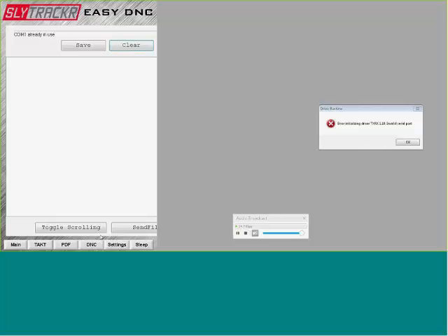So what we've done is integrate that into the tablet, which allows it to be networked versus the standard way of wiring all the machines into a big RS-232 switch box or some other form of wireless communication. It combines all of this into one neat package, and it works great because, for those of you that know, there's always problems with the communication because all the machines have different baud rates and stop bits and parity and so on and so forth.